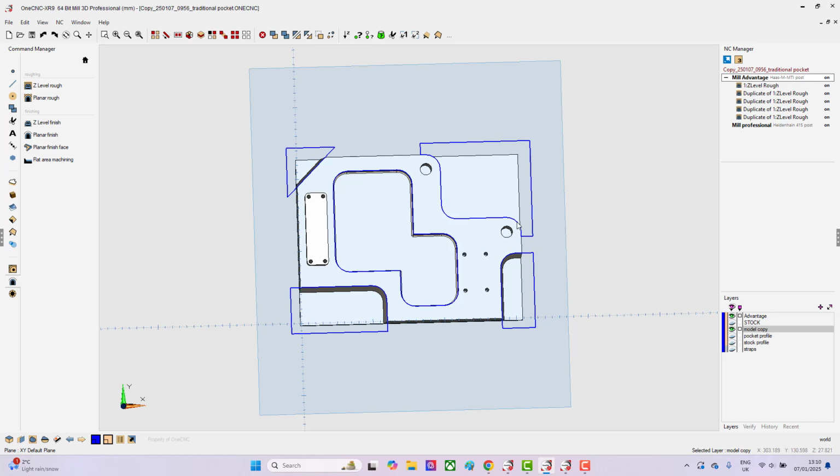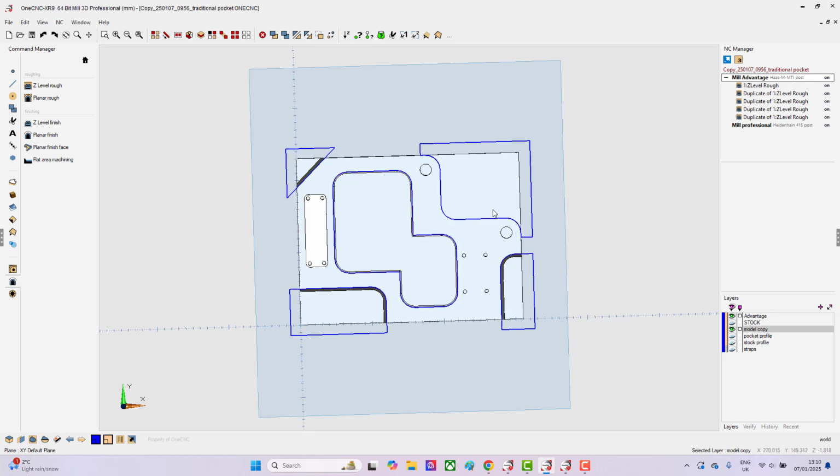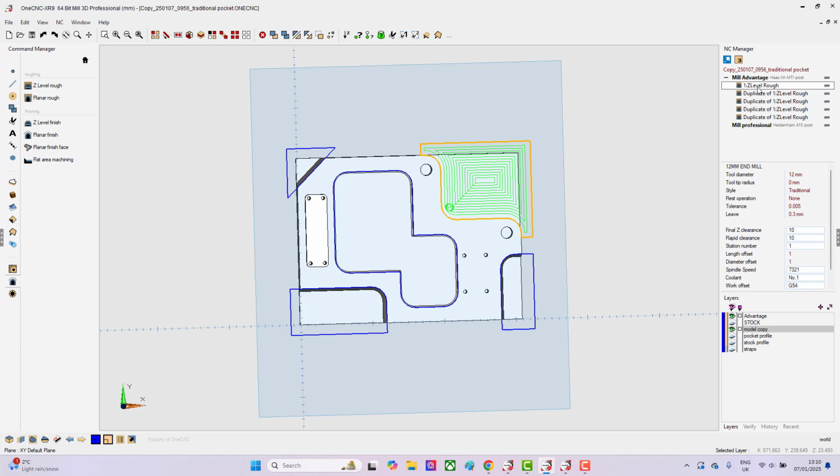And using traditional style toolpaths, there is no specific entry point. The software will calculate out its most efficient. So we would need to create 4 Z-level roughing cycles to remove the corners, and then we would need to use another Z-level rough to remove the pocket.